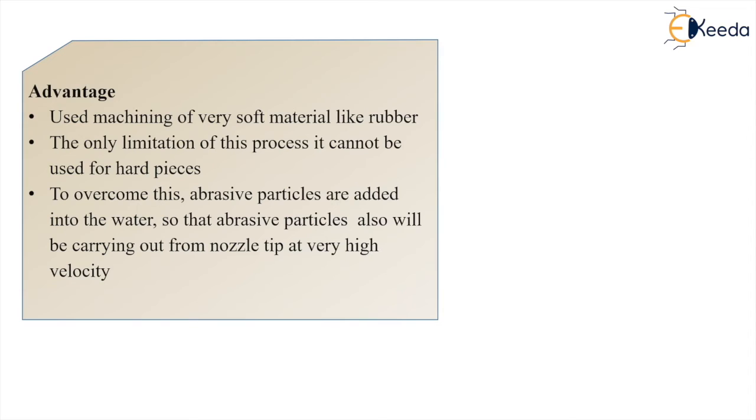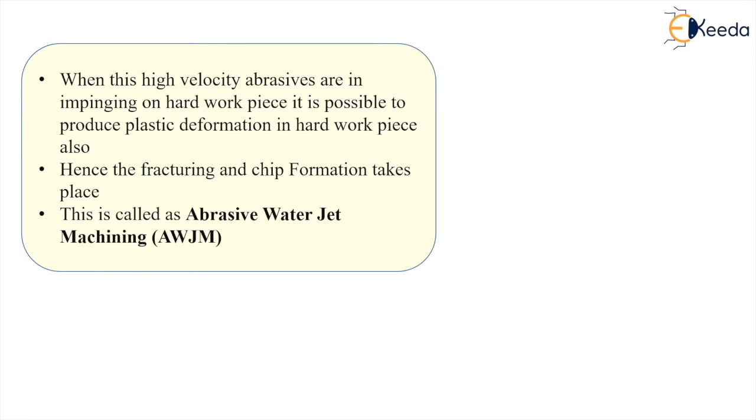Initially we saw water jet machining, but we have added the abrasive for the machining of hard workpieces. So this is known as abrasive water jet machining, AWJM. Understood? So in this video, friends, we learned about abrasive jet machining and its mechanics. The high velocity abrasive grains impinge on the work surface, causing tiny fractures, and the carrying gas or air takes out the dislodged small chips from the workpiece.